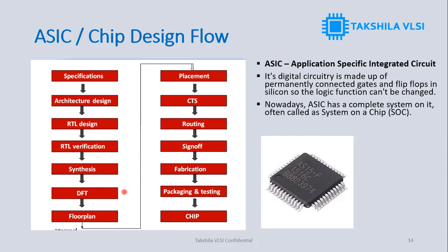So once your synthesis is done, next is DFT, design for testability. In this, we'll be testing the chip. So what are the things we'll do in the DFT? First, we'll insert one logic, the scan flop. So you can run the complete chip in two modes.